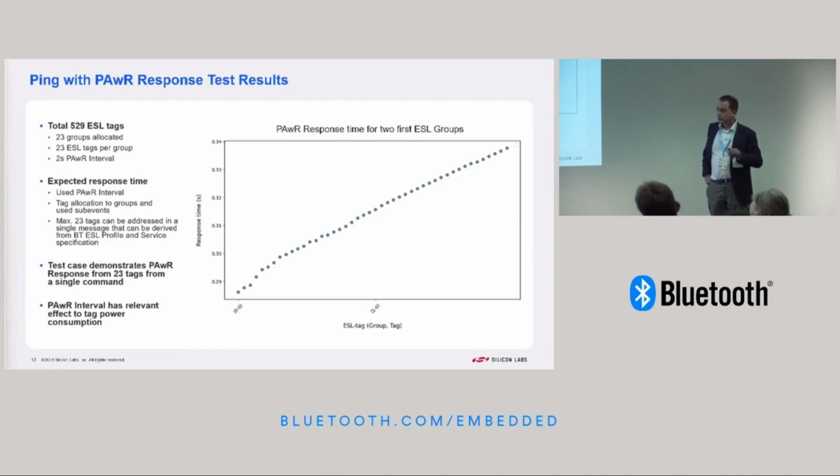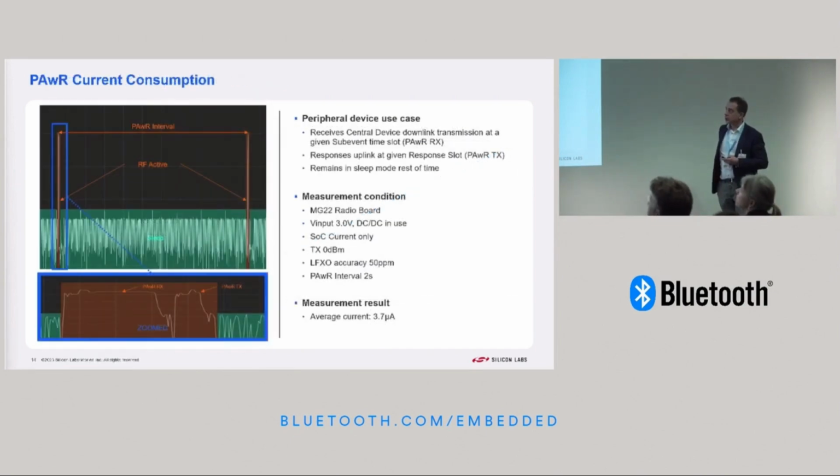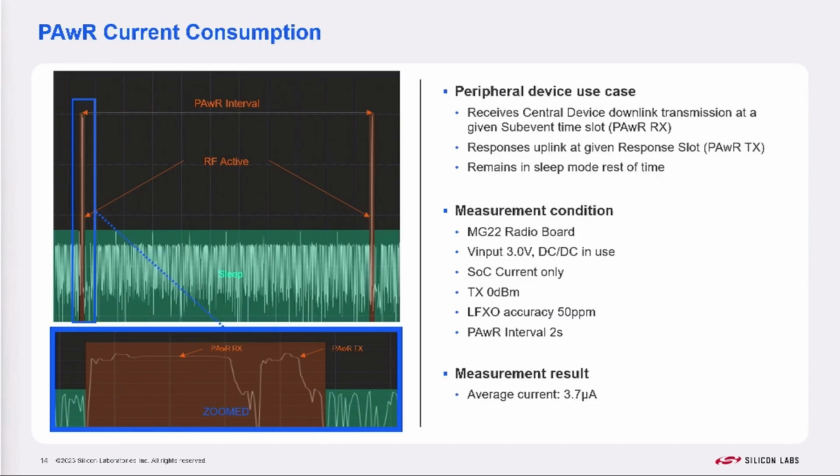But I think what is the more interesting thing here is that this was expected. That is what should happen. But what's the power consumption? I mentioned that low power is key, and most of the time the devices are in this synchronized mode, not even listening or getting a ping back, but just keeping the time synchronized and waking up. We took a snapshot of the power consumption here. First of all, let me explain the image a bit.